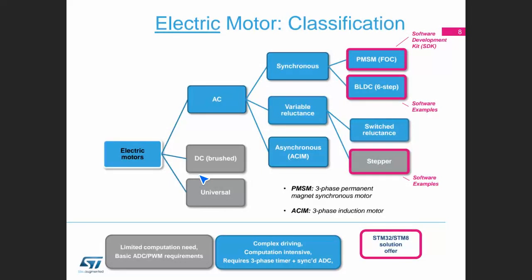This is important. In your professional life, your boss or your manager or your project may say you will control a DC motor, or you will control an AC motor. Firstly, you can start by searching the internet for which microcontroller family is good for your application. For example, for starting, I recommend ST. Why? Because ST evaluation boards are available. You can start with it. Its library is very advanced, etc.